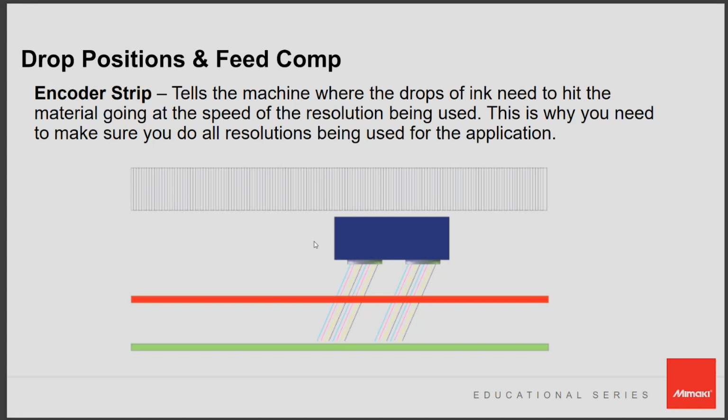But make sure that you're not applying any cleaner or anything like that to it, because that can damage the encoder strip. Again, this is very important for using the printer. If your encoder strip doesn't work, then you have to replace it.